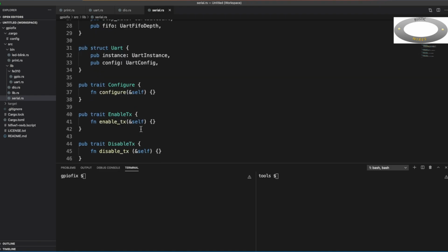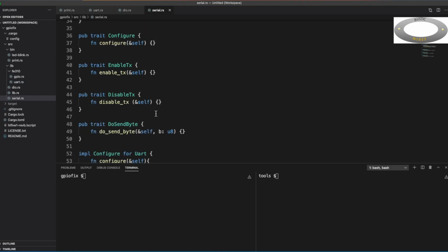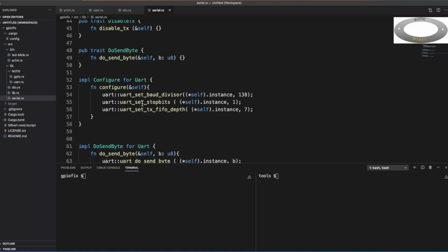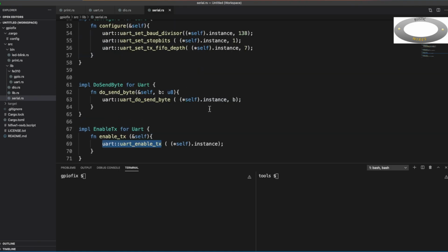But if you see, none of the code or the interface depends on any of the hardware specific functions, but inside the interface the hardware specific functions are called. So if I switch to another chipset, the only change would be in the lower level function. There is no need for any change in the signature here.